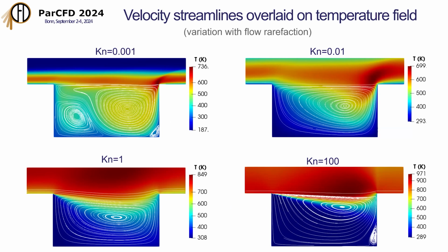And you're going from what we're seeing at the continuum end, going up very rapidly. Not much change in the Knudsen number, really, just getting into the slip regime here. And already we've got a very different flow structure going on. Kn of 100 here is essentially free molecular. That's where the molecules are only really impacting on the cavity itself and not with each other.